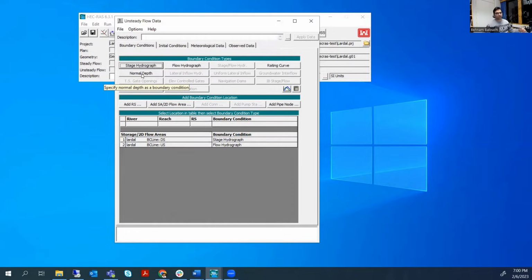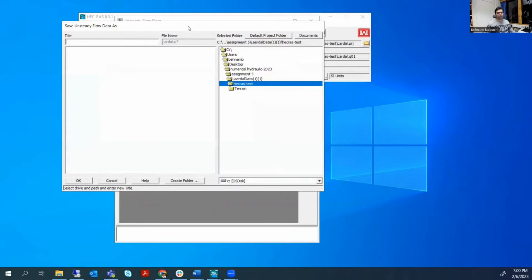If we have a backwater, for example, downstream we have a sea or ocean, maybe we have a backwater, so we should be careful about these data, because after running the model, we should calibrate the model. And for calibration, we should have some measured data from the field. I don't use any measured data from the field in this example, but you should find measured data and calibrate your model by matching, or having a good agreement between the measured data and your model data.